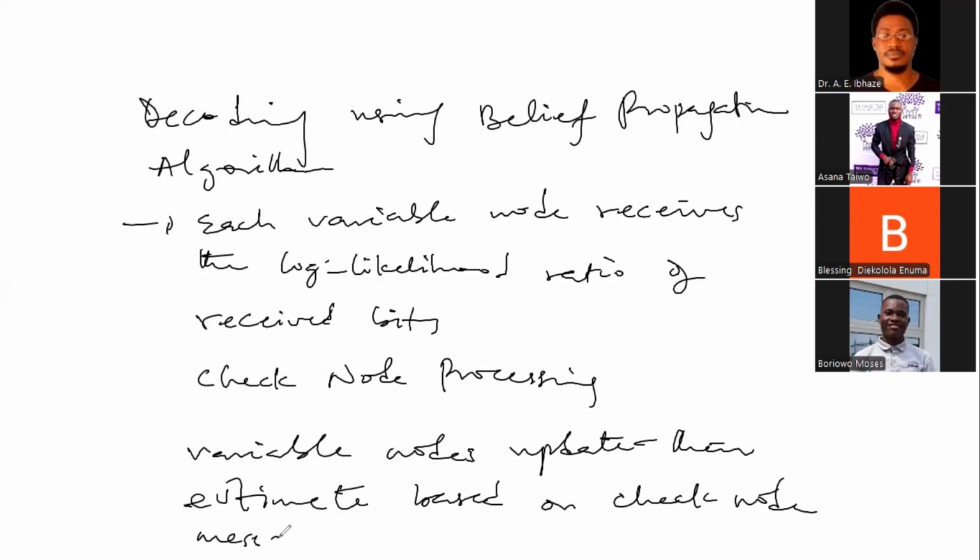We already have the equations that form this process, and the process will continue to repeat until we achieve the parity check times the code word being the same as 0, which is the decoding syndrome. Once this is the same as 0, it means there is no error in it. So that's why it's an iterative process.